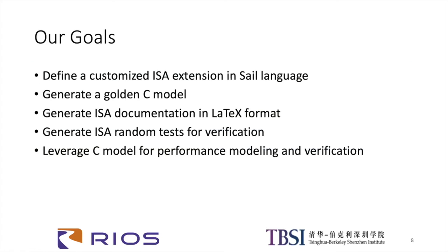Our goal is to define the customized instruction set architecture extension in Sail language based on existing RISC-V Sail. We would like to generate a golden C model, documentation, and random tests using the Sail tool. Also, we would like to leverage the C model generated from the Sail tool in our performance model and in our testbench code simulation environment. We treat this C model as the only golden reference. Thus, all the implementations such as the performance model and RTL must match this C model.